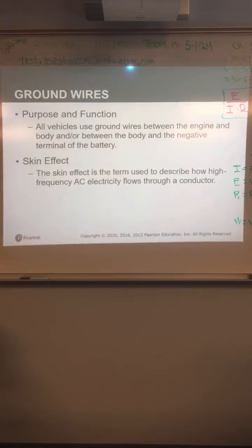Ground wires, extremely important on cars today. Cars have a lot of electronics on them. Ground wires are very important. All vehicles use ground wires between the engine and the body, and between the body and the negative battery terminal.